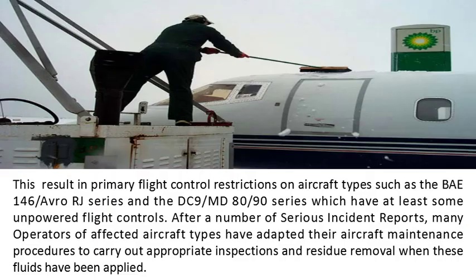This results in primary flight control restrictions on aircraft types such as the BA 146/Avro RJ series and the DC-9/MD 80/90 series, which have at least some unpowered flight controls. After a number of serious incident reports, many operators of affected aircraft types have adapted their aircraft maintenance procedures to carry out appropriate inspections and residue removal when these fluids have been applied.